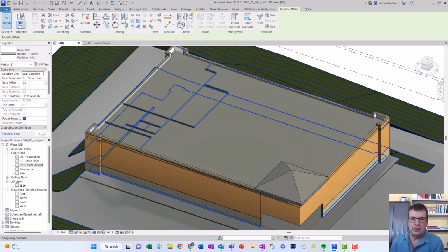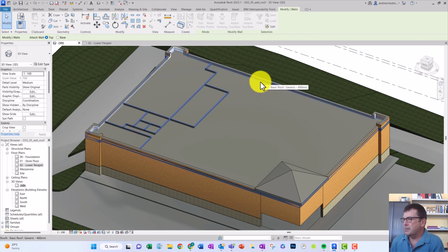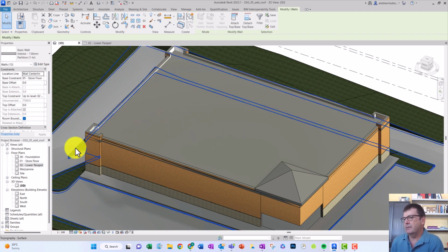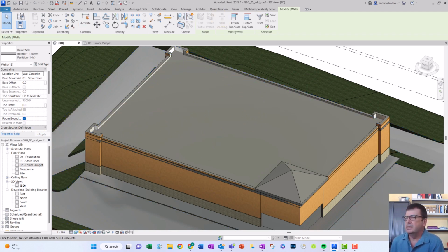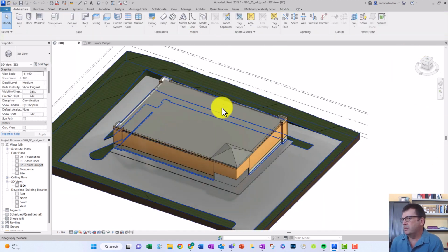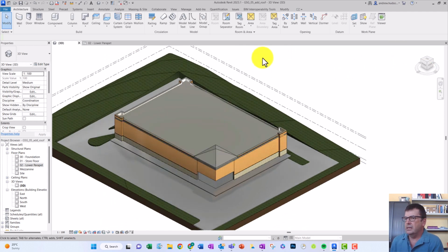And that should select all our interior walls. Then what we're going to do is click on attach top to base, like this, and then select the roof. We should just be able to pick up the edge of it, and it attaches those to the underside of our roof. Once we've done all that, we can go back to our architecture tab. We can click off it, and we have done our roofs. We've done a flat roof there and a sloped roof on there, and there is our building as it is at the moment. So that's it for the roof tutorial. See how you go with that, and we will look for the next one, which is putting doors in after we've done this.